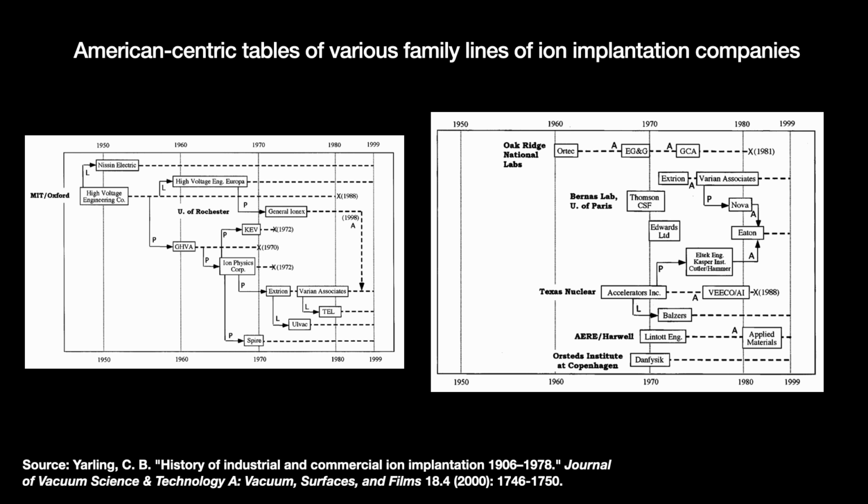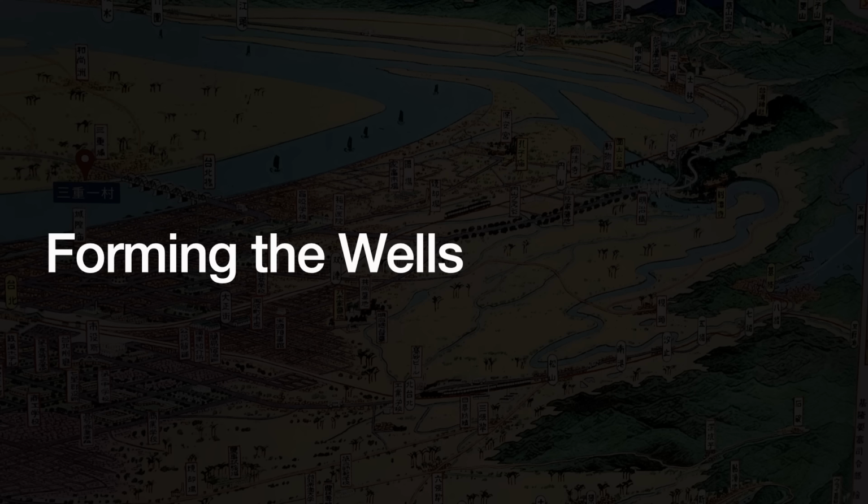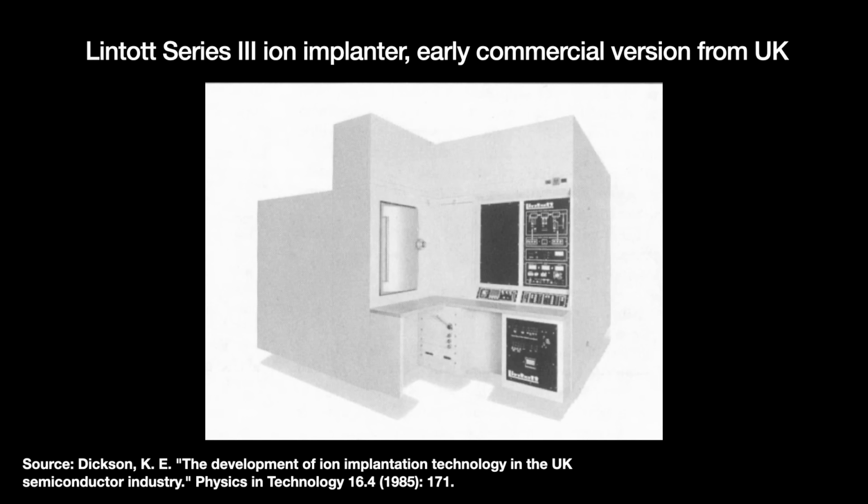The idea is simple, and the results more deterministic than chemical vapor deposition, which sounds like and probably is literal voodoo. But its process is still technically complex, as we are about to find out. We create the wells for the NMOS first. Remember opposites, so this means creating P-type silicon. The ion implantation machine hits the wafer indiscriminately, which is not desired. The ion implantation must fit a specific pattern, aligned to where the transistors will be on the chip.